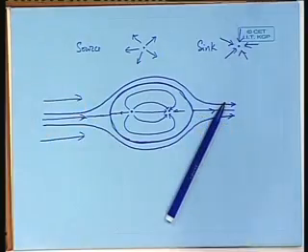So, now since the ship is a closed body, I can represent the ship by a number of sources and sinks. And what does it depend on? What is the strength of this source? The strength of the source is the slope of the water line. That means, I have large strength sources in the forward end and large strength sources in the aft end, and in the middle I may have sources and sinks with lesser strength. The source and sink distribution should be such that it represents the body.